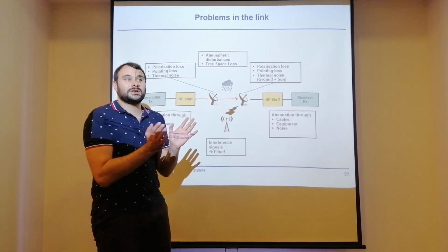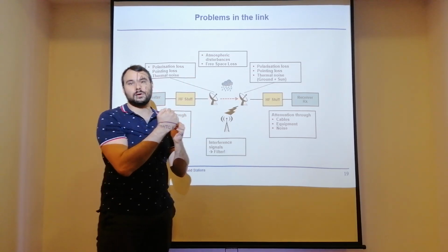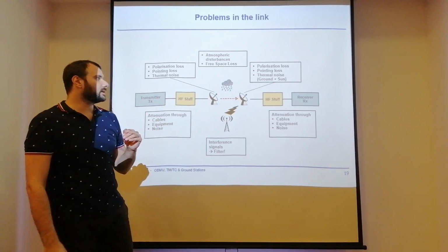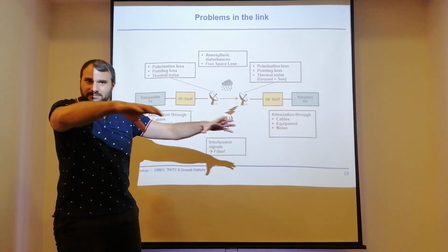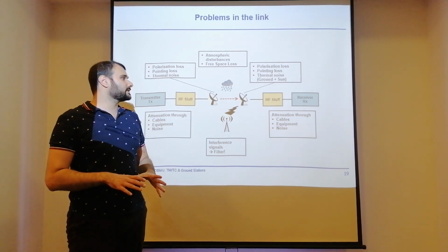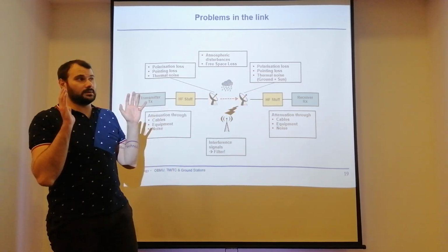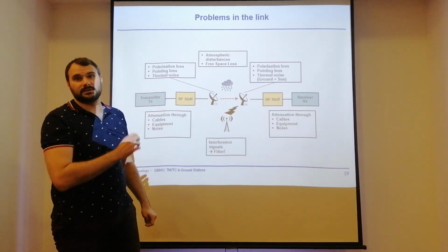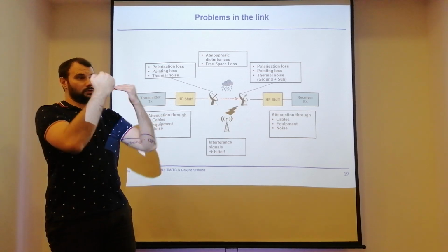Ideally, we are looking into cold space, so it should be a relatively low level of thermal noise there. However, we have the introduction of some ground-related noise in the surrounding of our ground station, and there might be even more thermal noise if we point our antenna, for instance, in the direction of the sun, which is quite warm, so it introduces additional noise.